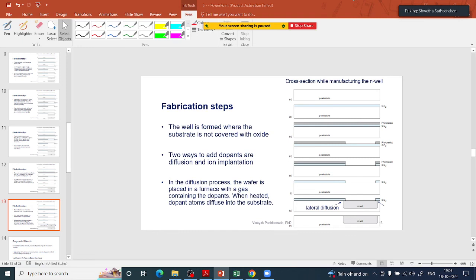Yeah, like I said, if you want to pass only, let's say, logic 0, we understood that NMOS is good for that. In that case, we are only using NMOS. Let's say we want to pass strong 0, then use NMOS. Then, suppose we are constructing an AND gate using pass transistors. Can we use NMOS only? Why would you do that? Don't you see the signal will be degraded, because we have seen that when we combine NMOS and PMOS in parallel, that acts as a good transmission gate to pass both the logics without degradation. So we use the transmission gate just to pass good logic at the output.